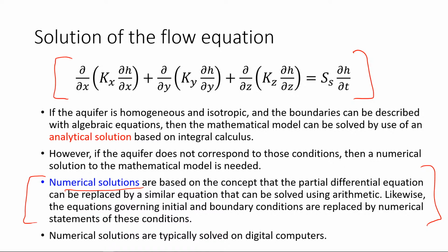But what I will show you in this lesson is analytical solutions. I will be showing you an analytical solution for a simple case. For confined and unconfined aquifers with 1D flow, we will see how the analytical solution for this groundwater flow equation will look, to find the head.